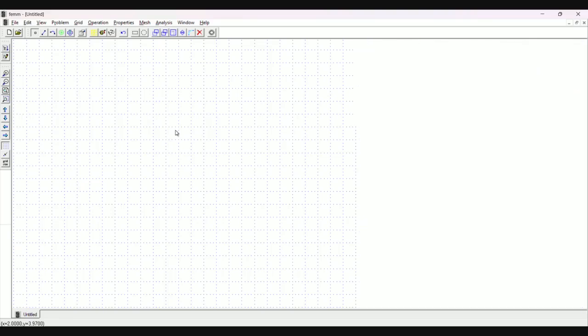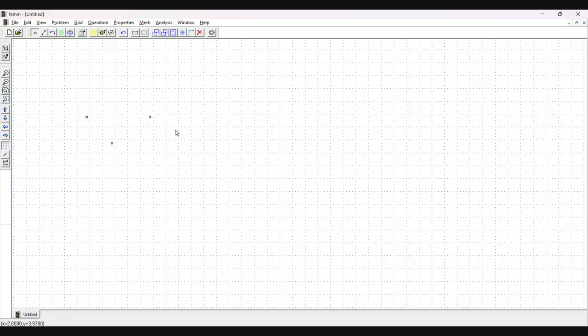By mistake I've added a point. You can just press Control Z and undo everything, so I'm trying that. See, one point has gone. If I press undo again, Control Z, this point should also go away, ideally. No, it returns back. FEMM only has undo once, only for the last step. So if you spoil your operations and do something wrong, you cannot undo it.